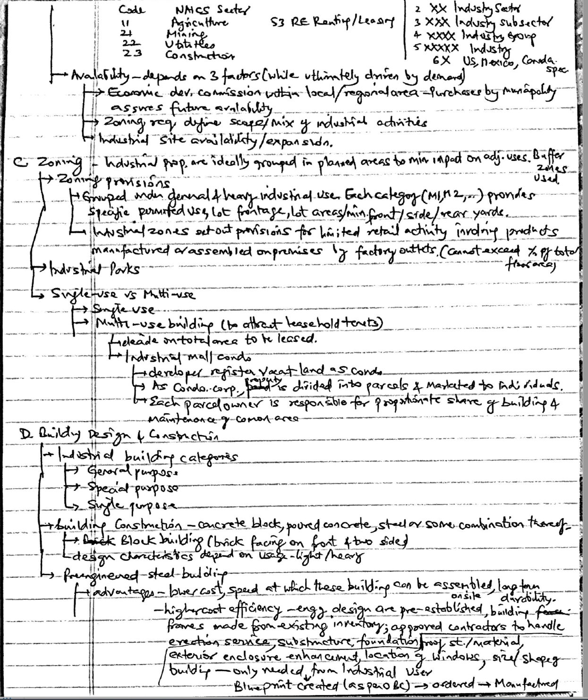Floor, wall, and ceiling finishes will vary, but at the basic level would include sealed concrete floors in the industrial area with vinyl or ceramic tiles for the office. Interior partitions would normally be drywall on metal studs, along with acoustic ceiling tile.